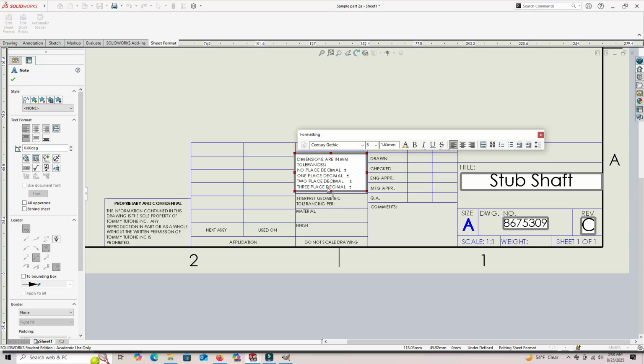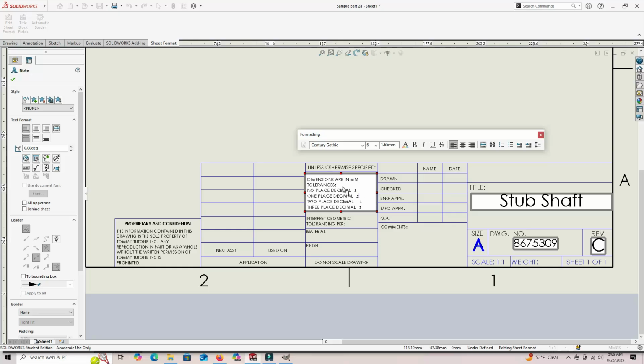Honestly, I don't think we're going to have anything down to microns in this, but if you were going to, you could have it here. Some of you may be wondering why the heck I just changed all that and what this even means. And if you're not coming from this from a machining or manufacturing standpoint, you may not realize that the way the dimensions are actually given on the print determines which tolerance we're going to use. So for instance, if a dimension just said 6 millimeters with no decimal places, we would use a tolerance that was listed right here. Let's say plus or minus